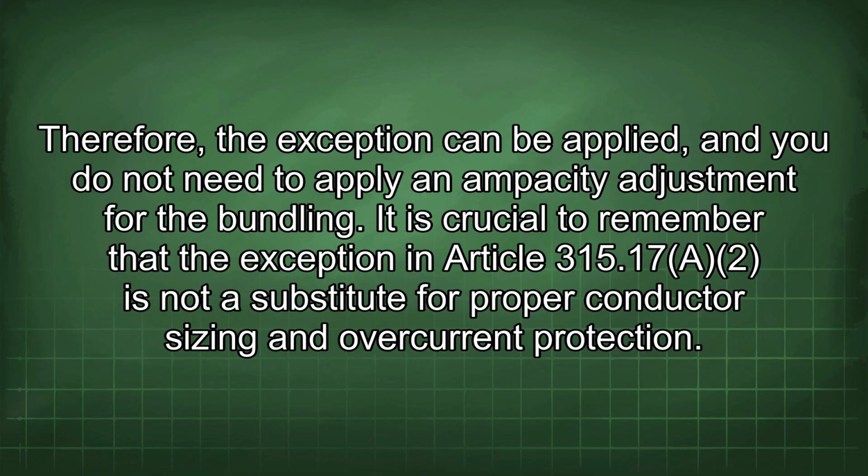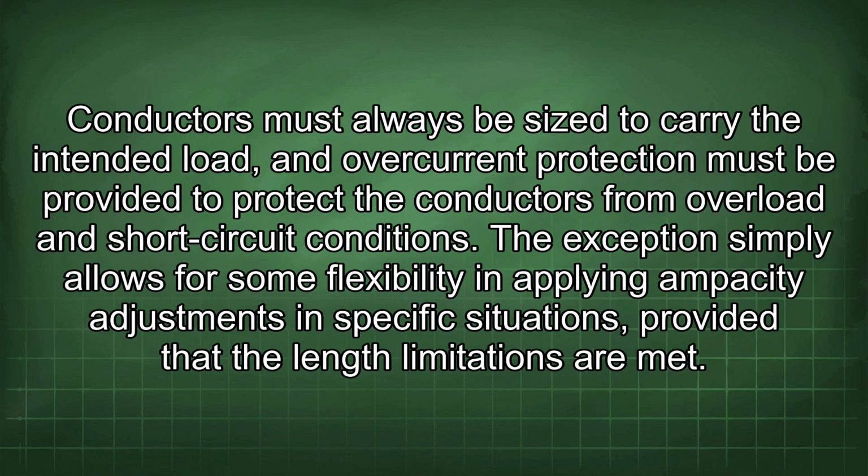It is crucial to remember that the exception in Article 315.17 is not a substitute for proper conductor sizing and overcurrent protection. Conductors must always be sized to carry the intended load, and overcurrent protection must be provided to protect the conductors from overload and short-circuit conditions.